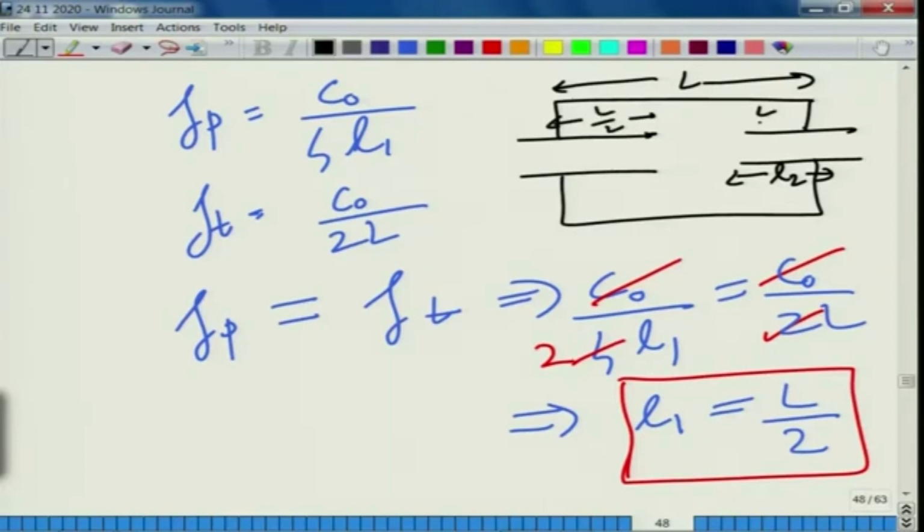So, that means if you have a resonator with length, so if this length is your L by 2 and this is your L by 4, so what would happen then? It would kill the first axial resonance, the second axial resonance due to this, the third one as well, but the fourth one it cannot eliminate.